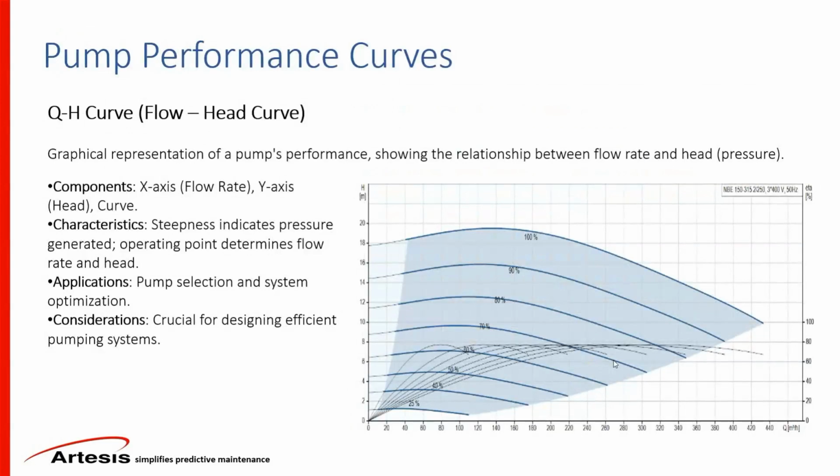We are going to look at the pump performance curve of flow and head, the efficiency curve and the system curve, so that this will all make sense. In combination, all these curves give us actionable outputs from the pump. We know what it's doing, and whether it's running efficiently, cavitating, or close to a shut-off head point, where the temperature of the pump gets higher and higher, risking damage to the pump bearings and seals as well as cavitation.